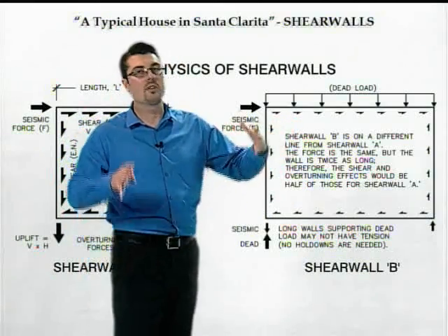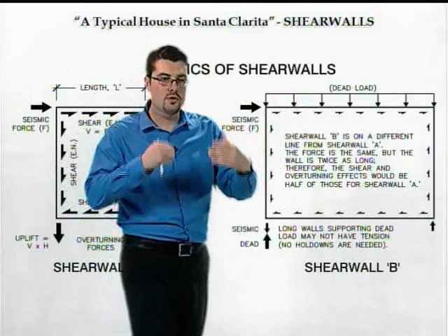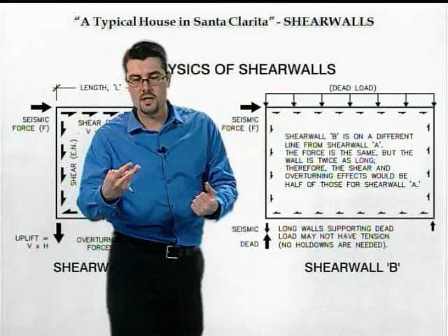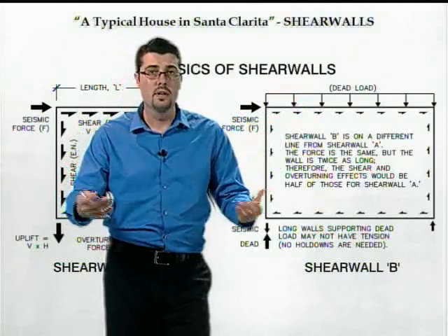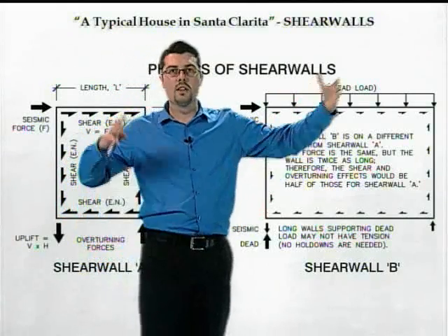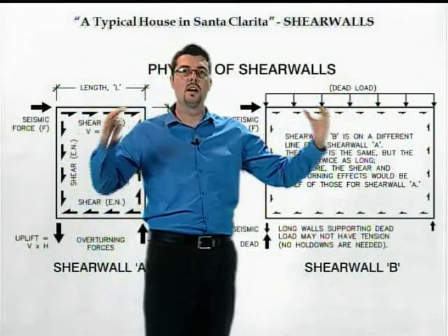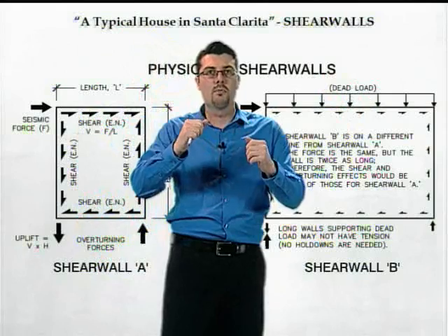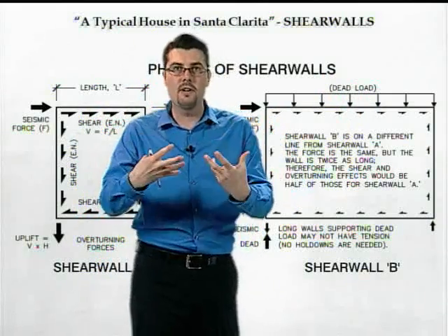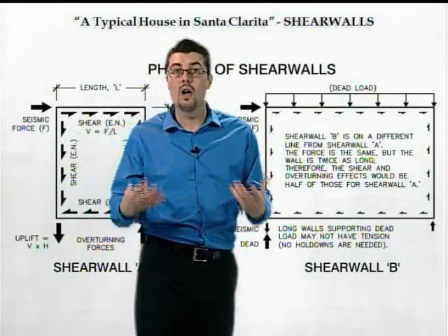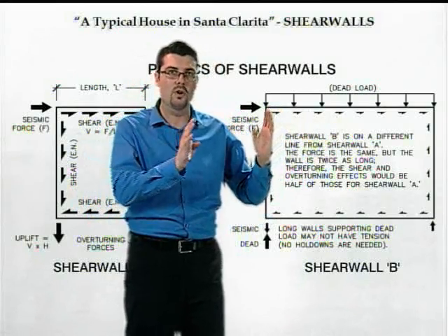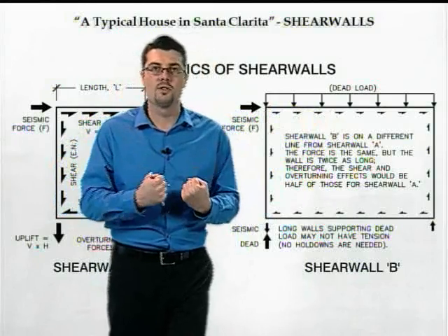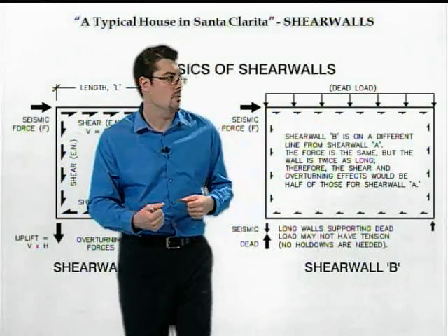The longer my shear wall gets, the less stress per foot I've got, and I can expect a lesser shear wall. As a designer or an inspector or a builder, when you see a long shear wall, you're probably not expecting a really heavily nailed shear wall. Whereas when you see short, slender walls, you're probably expecting to see heavy nailing, heavy hold downs. And that's why, is because the shorter a shear wall gets, for the same amount of force, the heavier that shear wall has to get, or the stronger that shear wall has to get per foot.